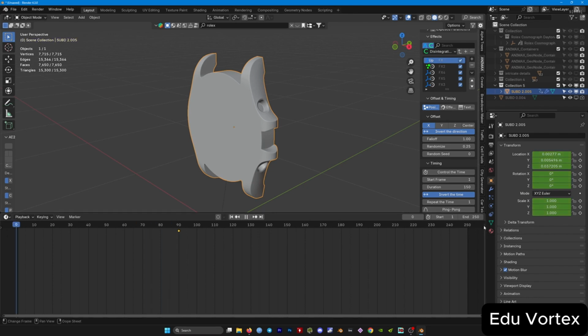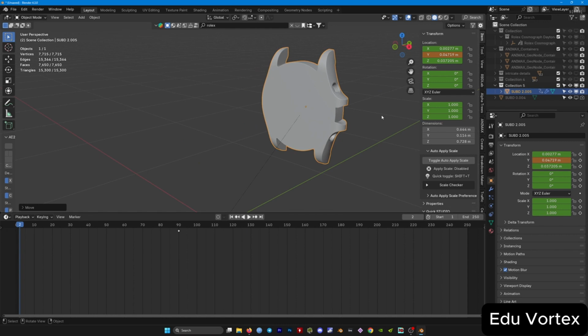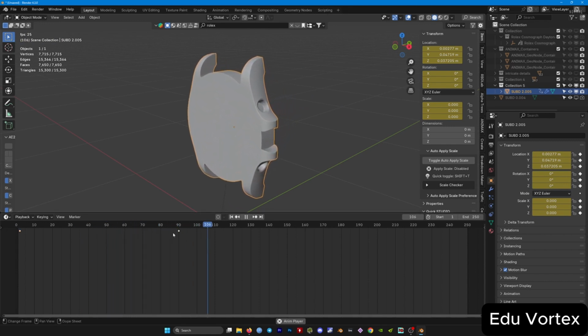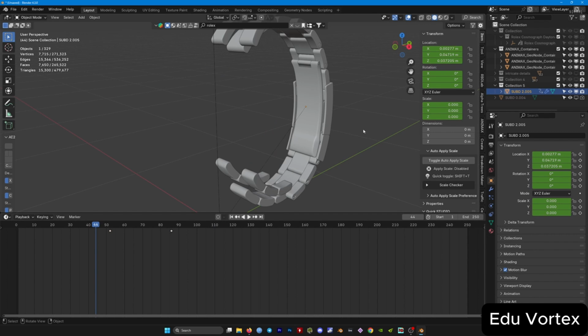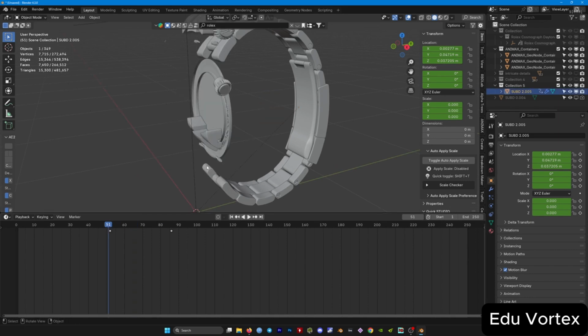and let's go to a different keyframe, preferably at the start in this particular animation. So let's push this back a bit and scale it down to 0 so that it scales up in the animation. To scale it down to 0, press S and then press 0. Press I to keyframe it. This is the animation we get. This looks good. Let's make it a bit quicker so that it appears with the rest of the animation. I think this is a little too far back, honestly.